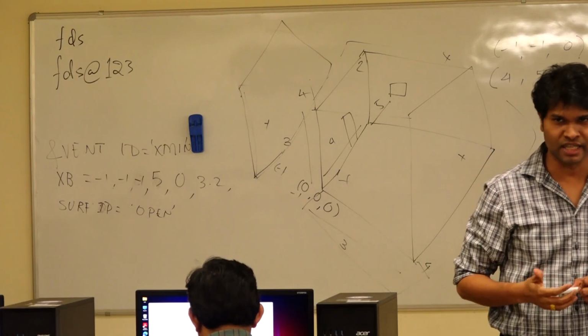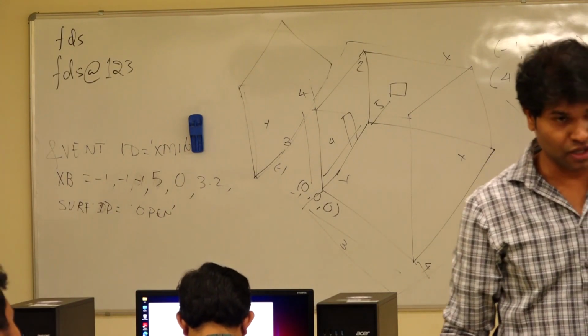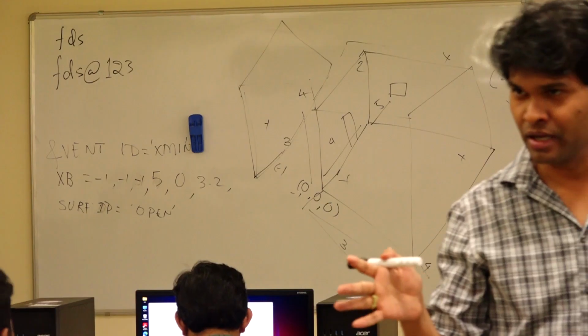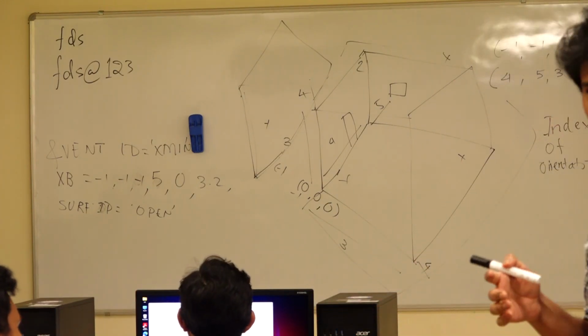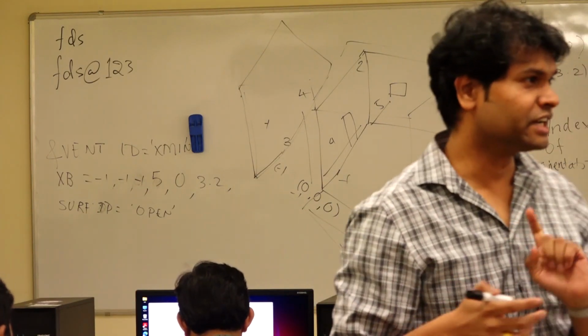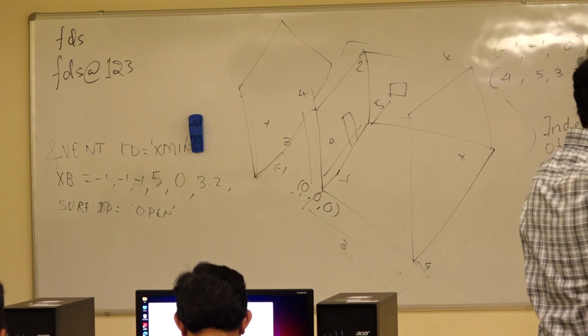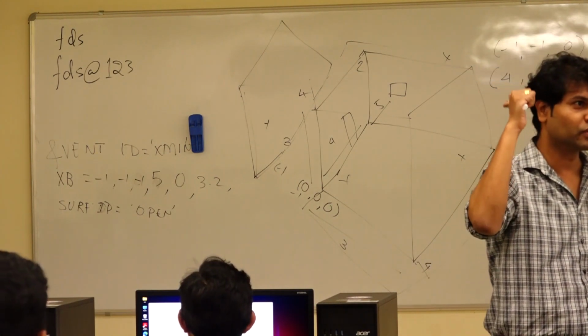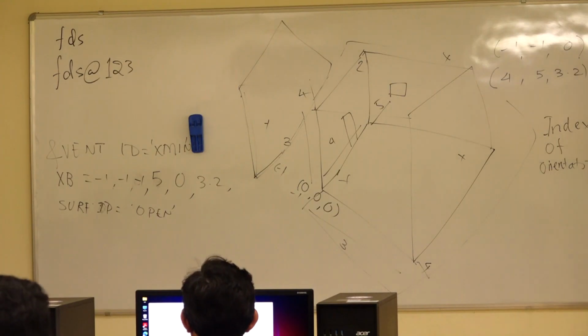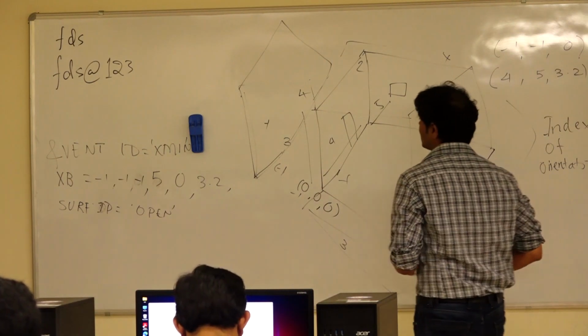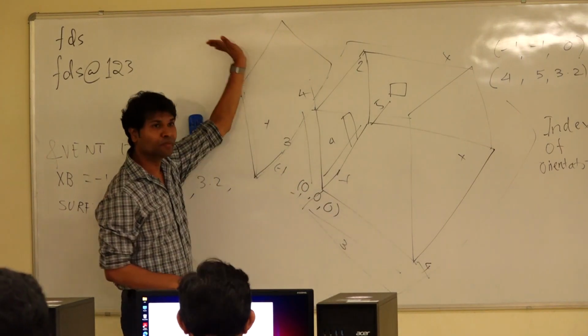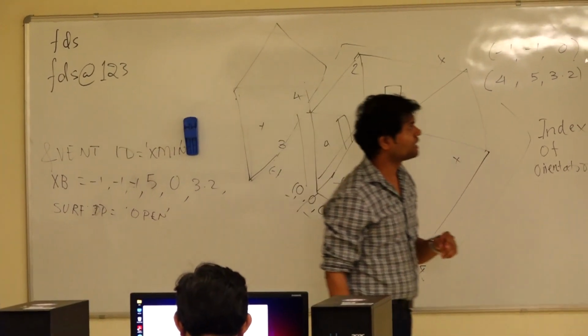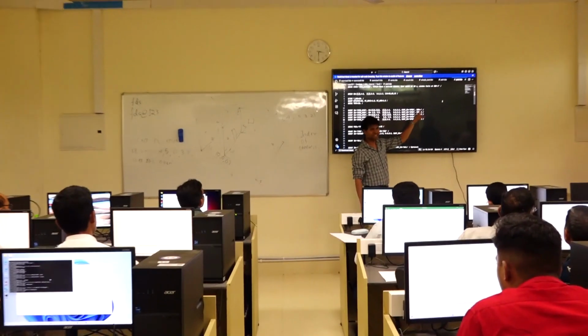And that is a very important concept, because if it's an open boundary, FDS needs to know which way it's open. Is it open towards the positive x-axis or the negative x-axis? So all the combustion products are going to flow out of the domain in the negative x direction. In this direction, your IOR is going to be -1.